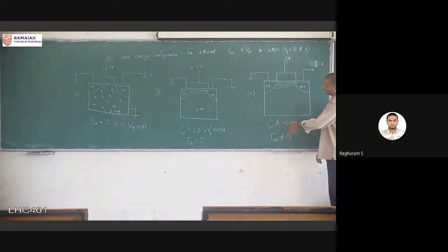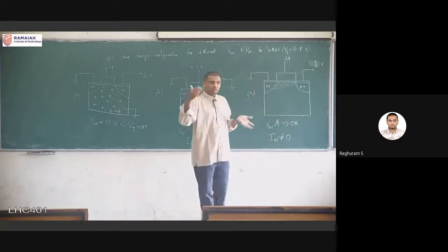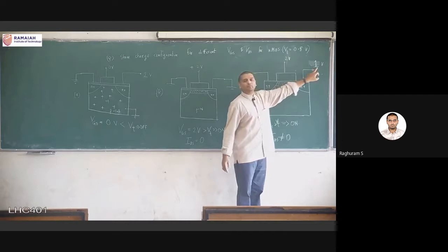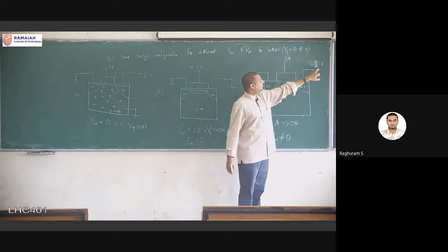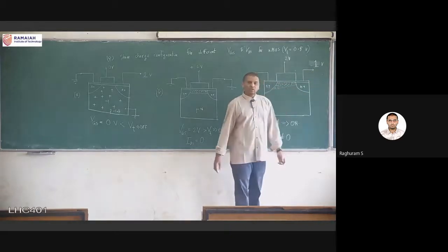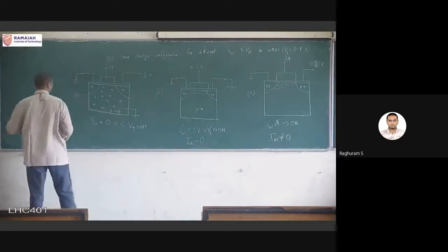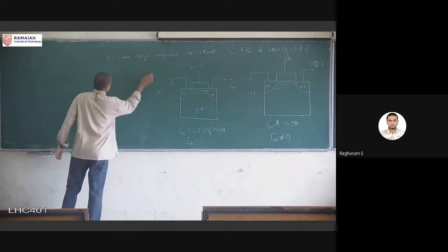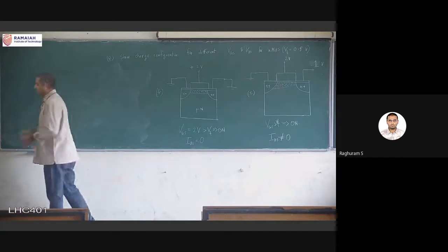Now we have a little bit more space. As you recall, in digital circuits, the range is 0 to the power supply. The power supply is 2 volts, so I can increase this a little bit more. Let us go one more step all the way up to 2 volts, which is the maximum value for drain voltage also, and see what happens to the channel configuration. Okay, so I'll just erase this diagram. This is the case D.